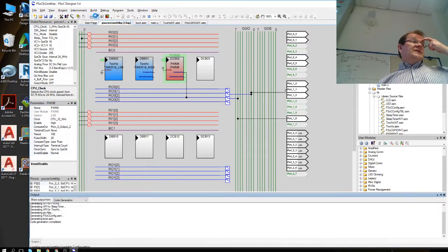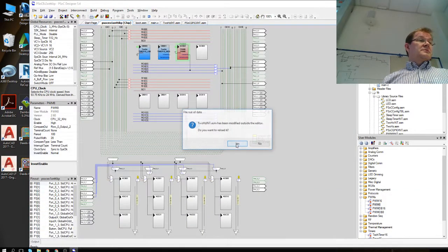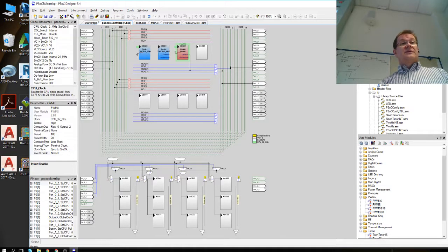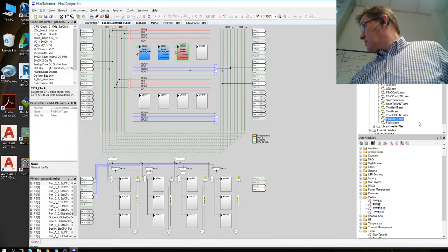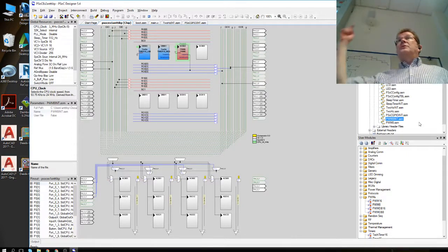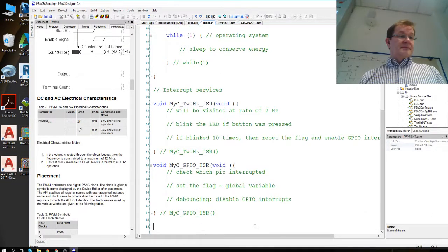And again, when you generate the configuration files, you will get also the PWM8 interrupt.asm. And now you know what you do. Either long call or long jump to your own interrupt service routine. And inside of that interrupt service routine, I'll just write a dummy routine here. Void dummy routine.